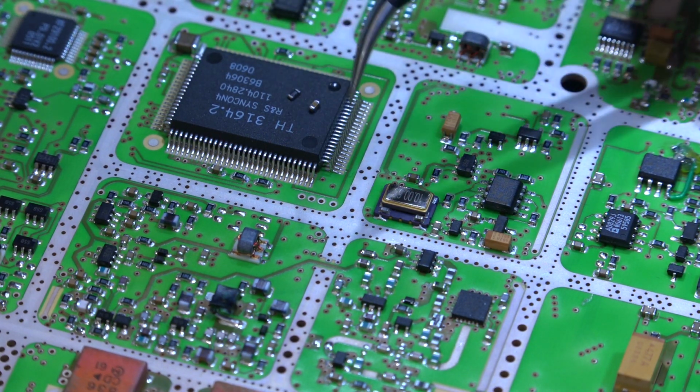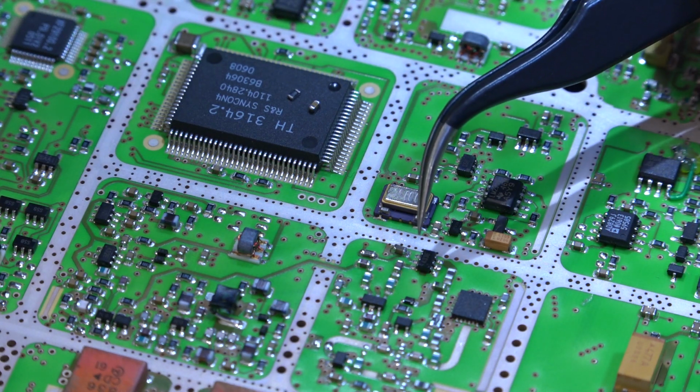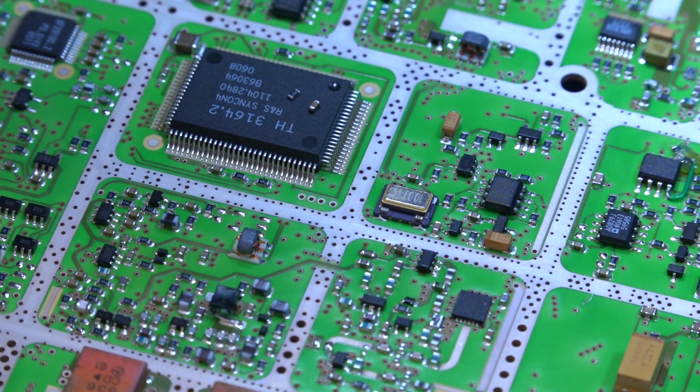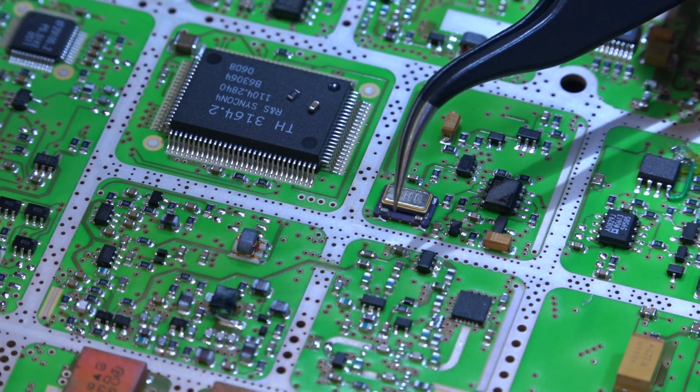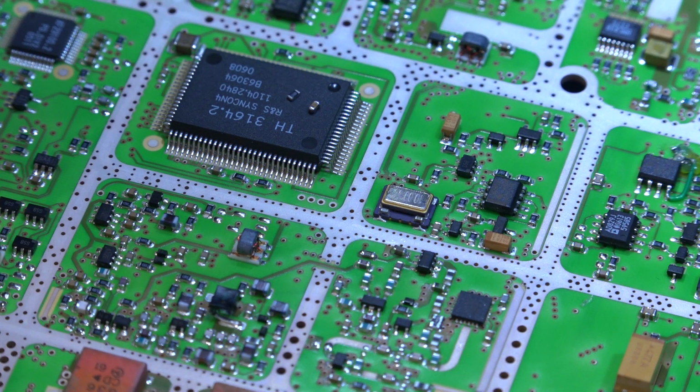So what ended up happening was I was trying to measure the resistance across this frequency divider to see if there was a short across it from its power supply to ground. And I was probing around this capacitor, and I noticed that sometimes when I pushed really hard against the capacitor to make a good contact, the resistance I was measuring would go from 5 ohms to 200 ohms. It would jump back and forth. And of course, 5 ohms is very, very small.